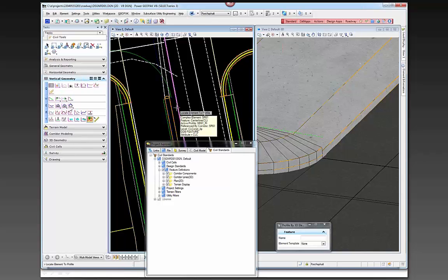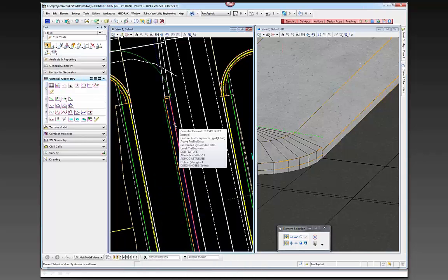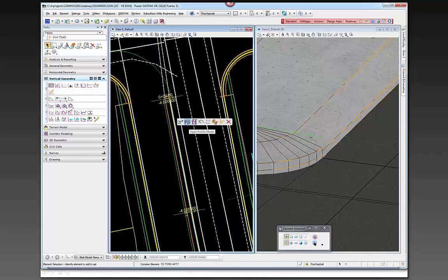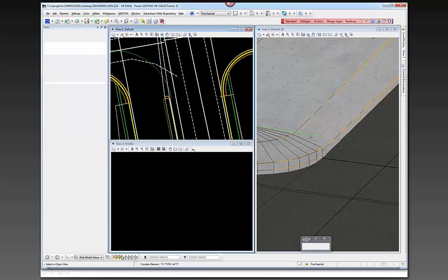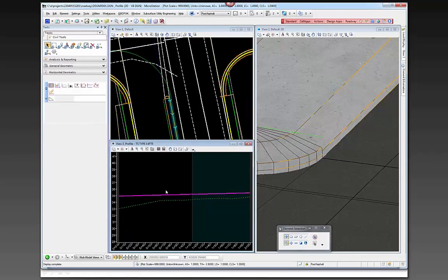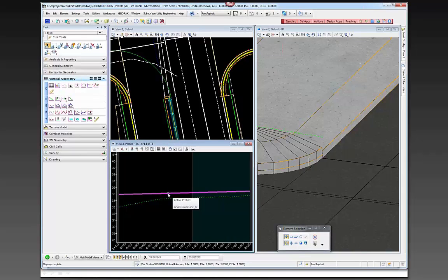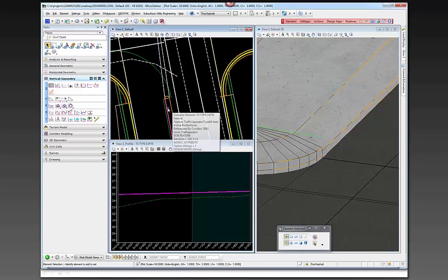And then once you select that line, it asks you for the 3D element that you want to apply the profile onto that element, which would be the 3D line string. And when you've done that, you can go to the profile view for these elements and click in the view, and then you'll see the profile associated with it from the actual 3D model. Because remember, these are just 2D lines until we add the profiles from the model to them.